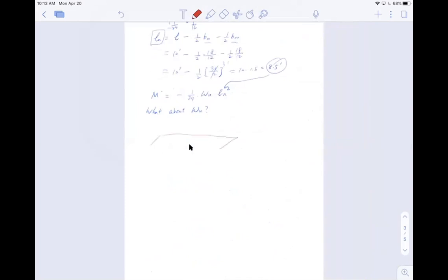So this is my 1 foot slab. And to be specific, this is the strip, the 1 foot strip I was talking about. So this is 12 inches. All right, and don't forget, it's per foot. Whatever loading you have, it is per foot. Okay, so now what is this per foot business? I have a distributed load on top of it.